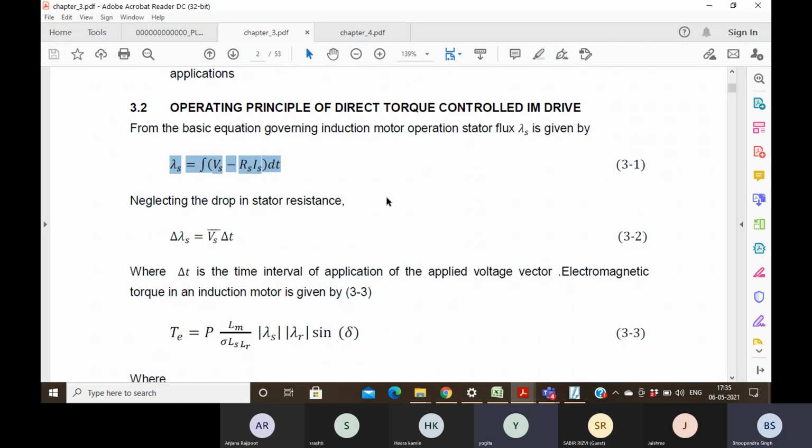Yes, because this theory which we are going to discuss will have to be implemented on a digital controller. Finally, you are going to build a drive, and whatever algorithm you develop for that drive, you will implement with a controller on a real motor. That controller will obviously be a digital controller, so you will be dealing with digital quantities. So all the algorithms we are talking about right now must be discretized so that the controller can understand the language you are going to implement.